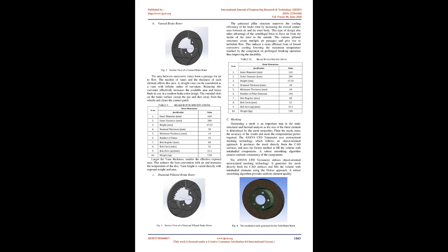We have performed static structural analysis and steady-state thermal analysis of 3 types of disc brake rotors. These modules in ANSYS give the total deformation and temperature distribution of the disc after applying brakes at 120 km/h, 33.33 m/s, single stop. B. Geometry.